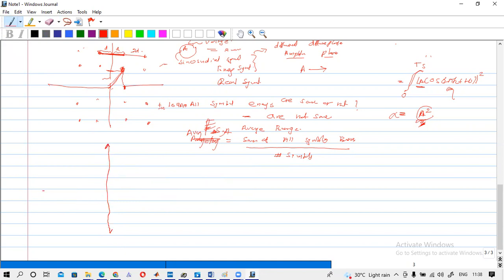Here we have the constellation diagram. In the constellation diagram we have 16 points, because this is 16-QAM. We have 4 here and 4 here, 16 points. If you consider the distance between two adjacent symbols, it is the same.